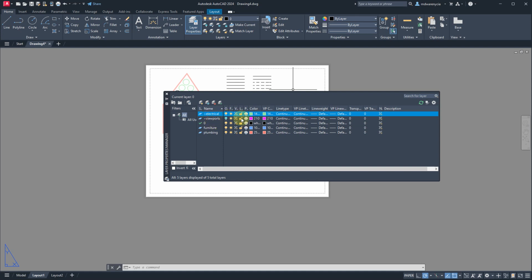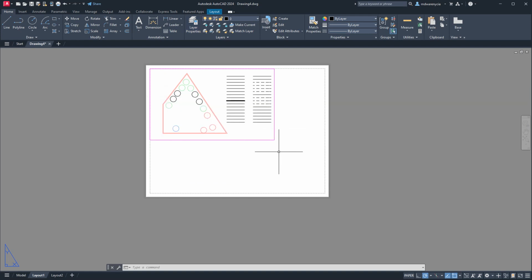All right. So anytime I'm getting ready to print or whatever, I know, okay, I need to make sure that these are off, kill these. Or in the case of printing, don't print them. So there's different settings here that you can change. Keep an eye on them. Try not to let them mess you up. But again, it's a personal preference of just putting the viewports on a viewport layer and then hiding that layer. It looks a little bit cleaner, especially once you have a whole bunch of elevations in your drawing.